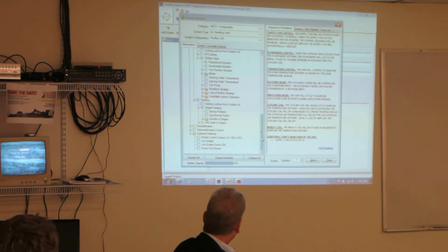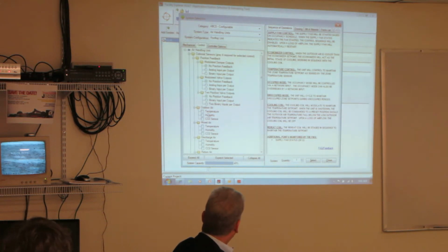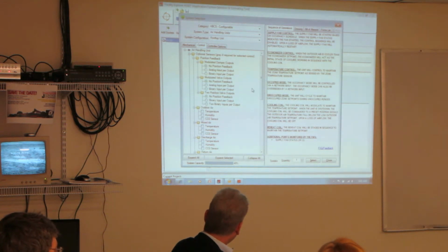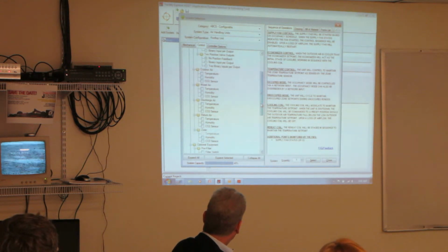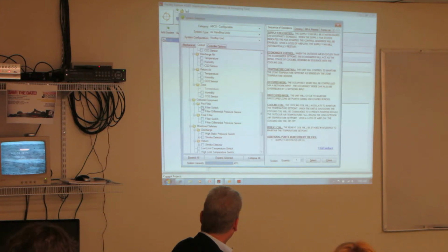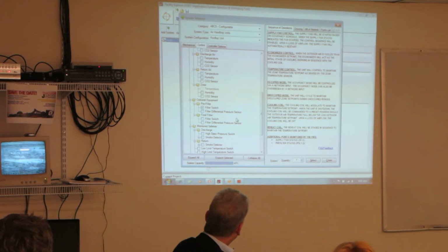We'll just leave those kind of the same. There's extra little features if you wanted to monitor some things, or if you want to do humidification or dehumidification. All of that's available in this software to configure your controller. If you want to monitor some extra inputs and outputs from outdoor temp and humidity, if it wasn't part of your standard sequence, some filters. We want to monitor the filter. So you would add a filter switch in there. And down here, then it added that pre-filter status.